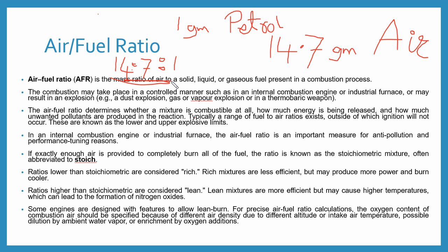The fuel can be burned in the combustion chamber even if the air fuel ratio is somewhat greater or lower than the stoichiometric ratio. But if the mixture ratio exceeds a certain limit, combustion is no longer possible. So this limit is called the limit of inflammability, which is the range in which combustion takes place. For petrol, the range of inflammability varies from 9 to 20 parts of air to 1 part of petrol.